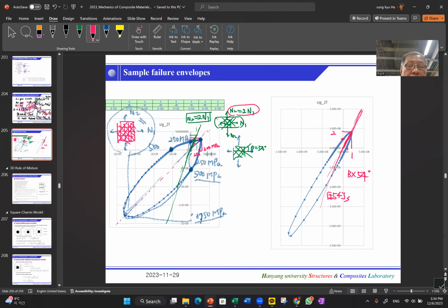No, we had one more, right? To make the same 54 and symmetry, 8 plies. And then again, this is about the same ratio. I mean, the 1:2 ratio, giving us the highest strength. That's why biaxial 54 is always the highest strength for the pressure vessel.